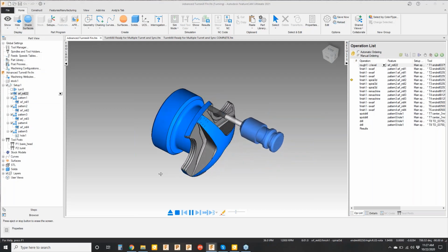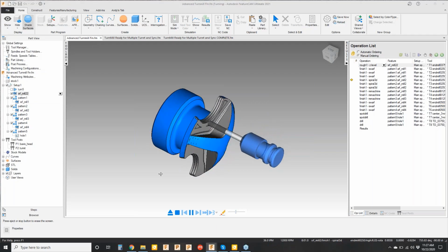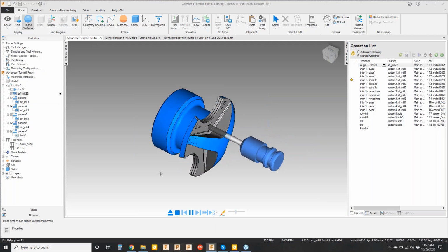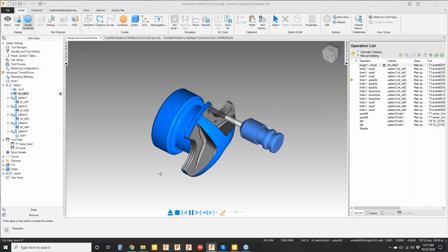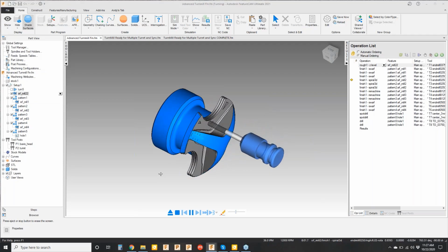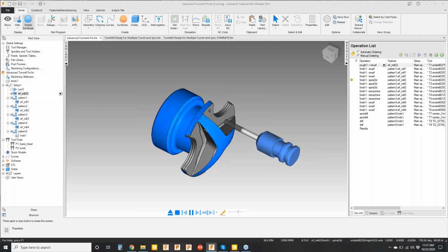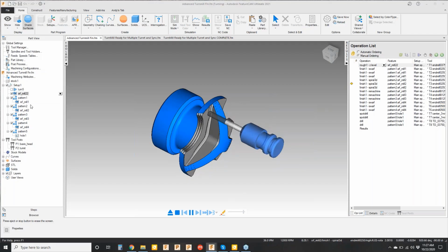So it's the same stuff that's in the regular milling documents is also here, but you notice the C-axis is in play if we want it to be, right? We can certainly lock that, keep rigidity. I'll go show you guys the setting here in just a few minutes, but just want to give you an idea. This was programmed once, and then it's patterned to the other faces. Okay, so we see this repeated 3 times.